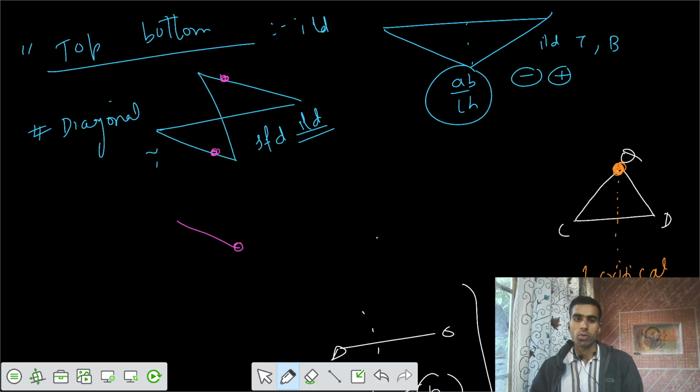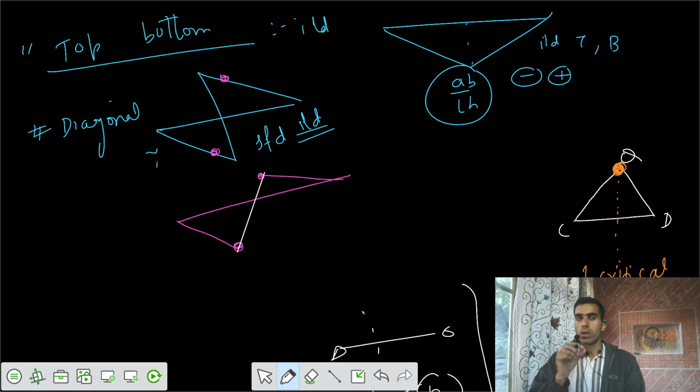We have this joint and one more joint here, so accordingly we get these two different values. Then we join these two by a straight line. So this is our ILD. From one of the critical points we have the ILD downwards, and from the other critical point we have the ILD upwards. That can be vice versa also. So this is the general diagram for the ILD related to diagonal members.